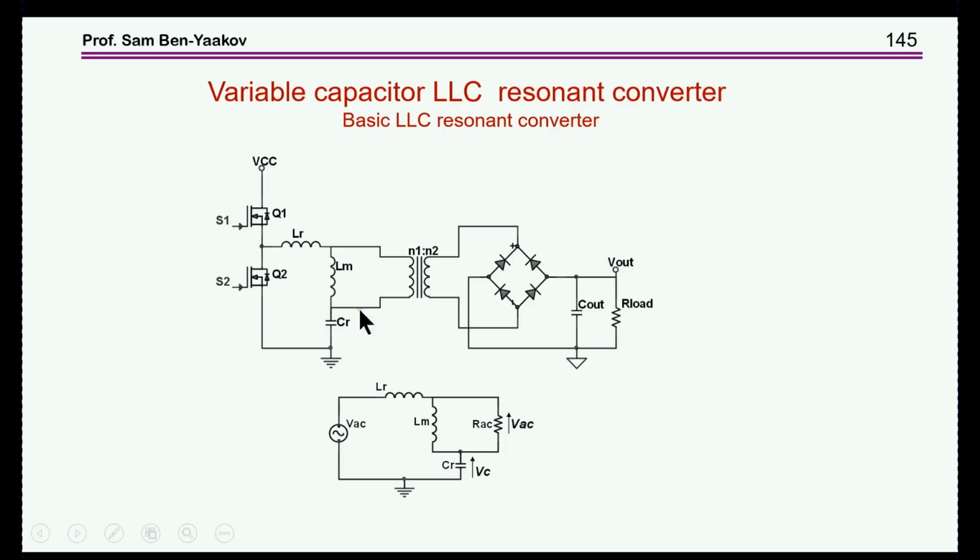What really matters here for the power is the first harmonic of the current and the voltage. And so you don't worry about the higher harmonics or the nonlinearity here. So this technique is used to convert this part into a linear circuit that you can now analyze.